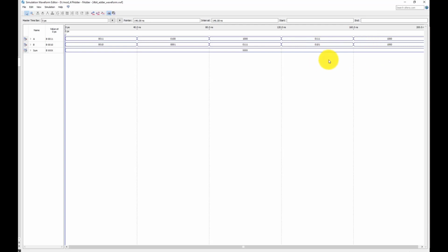But because we have a limited number of full adders, we will get an invalid result, which will equal 0. Why? Because 16 is 1 and 4 zeros at the end, and our circuit will not be able to display it. Let's consider it something similar to a calculator.